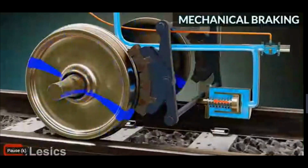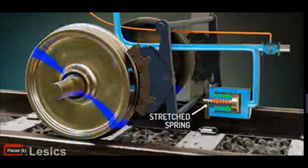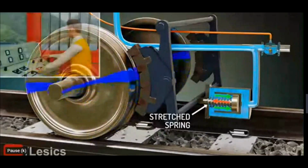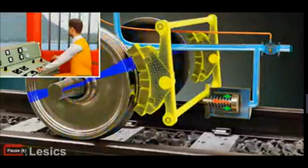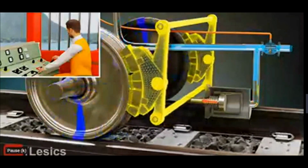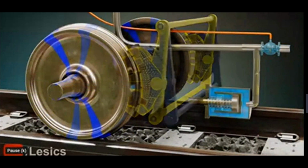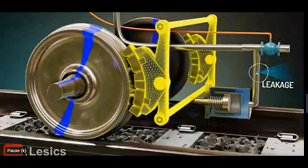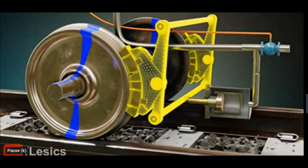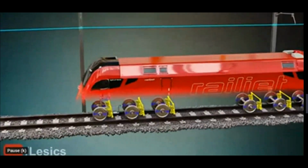Here, the spring force and compressed air forces are acting on the piston in the opposite directions. The interesting thing is that when the driver releases the air from the cylinder, the stretched spring pulls the piston towards the wheel and the brake gets applied. This brake system also provides security in the case of air leakage or broken compressor. The brake gets applied automatically as pressure releases. The pneumatic braking system is fitted under every coach for each wheel pair.